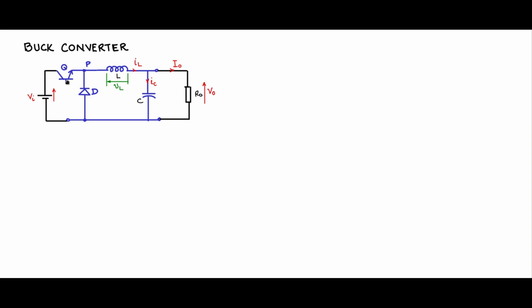So when this Q1 is made on, you will see that the current flows in that direction, charges up the inductor and then back. And when you switch off Q1, the inductor current will pass through this and this and freewheel through the diode automatically, and the energy will start discharging, and therefore the falling slope in the current. So this is how the switches are selected for a converter, for any general converter.